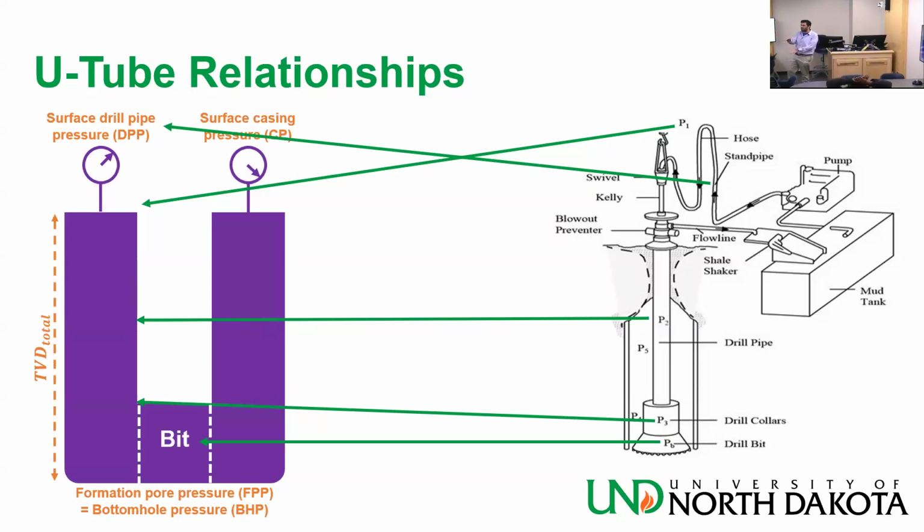I mean, how tall is a bit? Like a foot and a half? You don't gain a lot of pressure from hydrostatic, but you lose a lot of pressure because of friction across the jet nozzles. And this pressure is very important.